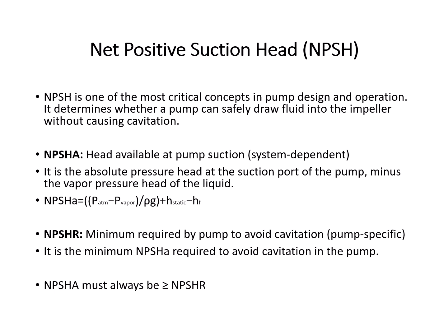Net positive suction head. Net positive suction head is the bodyguard. I always call it the bodyguard against cavitation. You need to ensure that the suction side of the pump has enough pressure to keep the fluid from flashing into vapor. So net positive suction head is one of the most critical concepts in pump design and operation. It shows whether a pump can safely draw fluid into the impeller without causing cavitation.